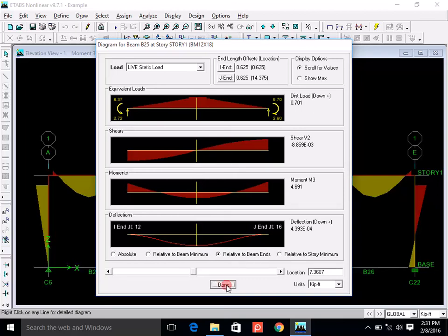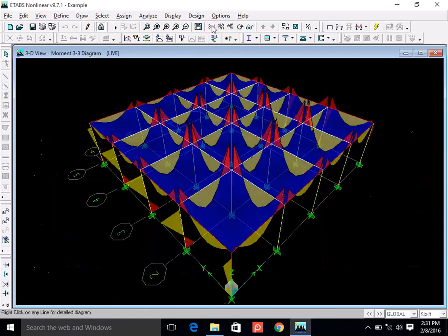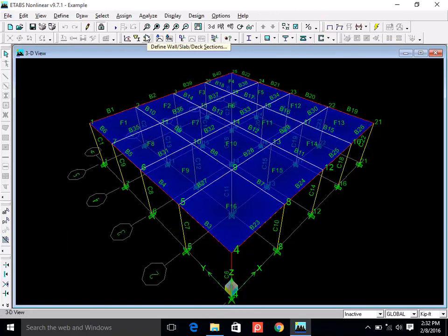Okay, the point I want to make is about meshing. We have to discuss the results, but before that we were actually looking at the meshing and the connection. So that's what I want to focus on right now. If you want to switch off these bending moments, you can hit this button, show undeformed shape, and it will be back. Okay. So what we saw in the deformed shape was that beams and slabs were not connected to each other, right? That's what we saw. How can we connect them and make them behave like in real life? For that purpose, we need to use the option of meshing.